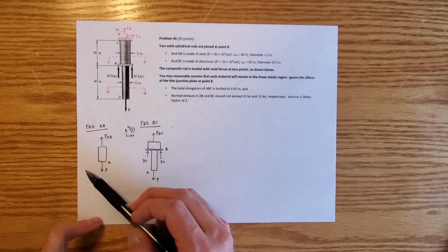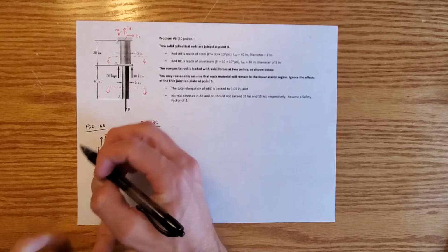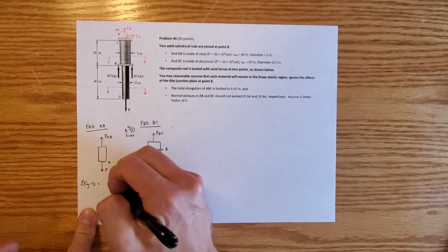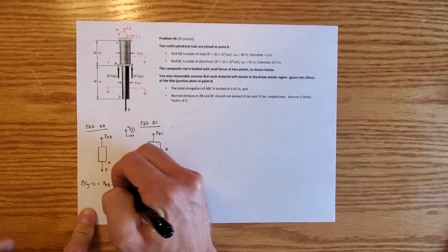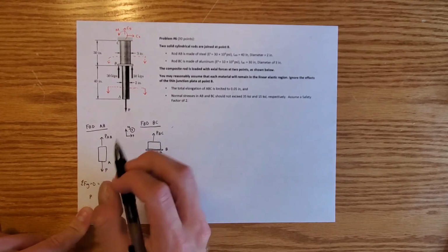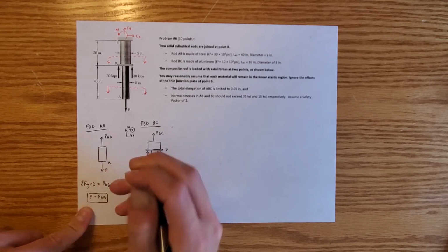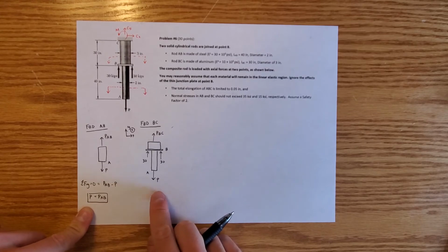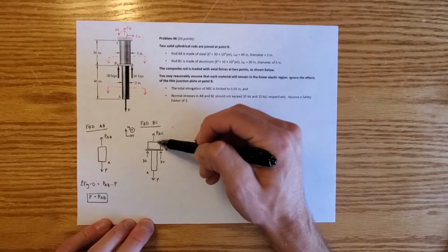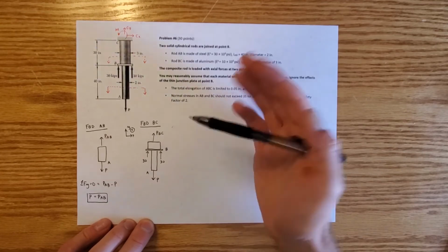So we look only at the normal force, and given our XY axes as shown here, it's pretty clear that when we do a sum of the forces in the Y, if this piece is at rest, then we have PAB up minus P. This tells us that the applied load P that we're looking to solve for is equal to the force felt inside of rod AB. This is going to be important later on. When we look over here and do a sum of the forces in the Y on rod BC, our free body diagram shows us that we have PBC going out of the rod, which we always assume. We're drawing it in positive tension.